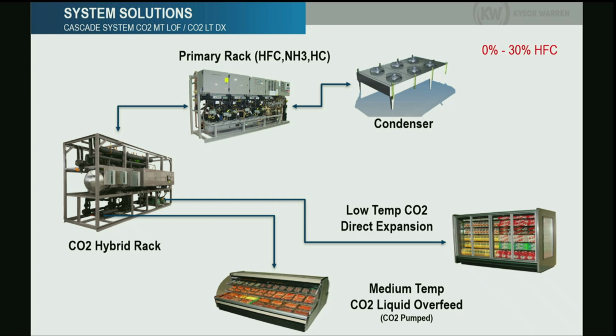So it's still considered the hybrid is still considered a cascade? It's still considered a cascade, yes. Because this HFC is condensing the CO2 here, yes. So you have pumps there though? Yeah, but the pumps take the liquid from the tank once after it's condensed. So this is still a cascade system, yes.